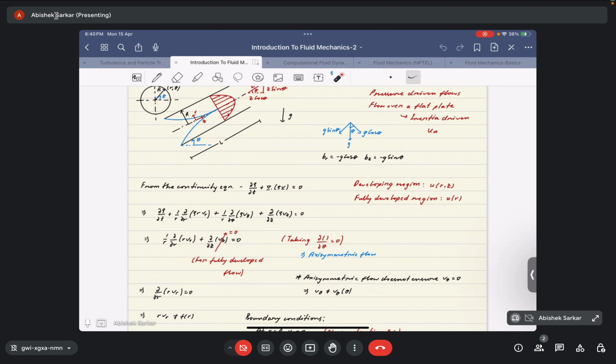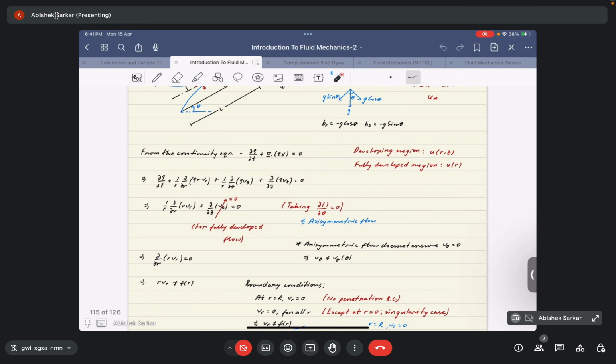Since the continuity equation is a single equation and does not have any components, we write it in terms of the velocity components in the cylindrical coordinate system. So you can write ∂ρ/∂t + (1/r) ∂/∂r(ρ r v_r) + (1/r) ∂/∂θ(ρ v_θ) + ∂/∂z(ρ v_z) = 0. And we take some assumptions for solving the problem.